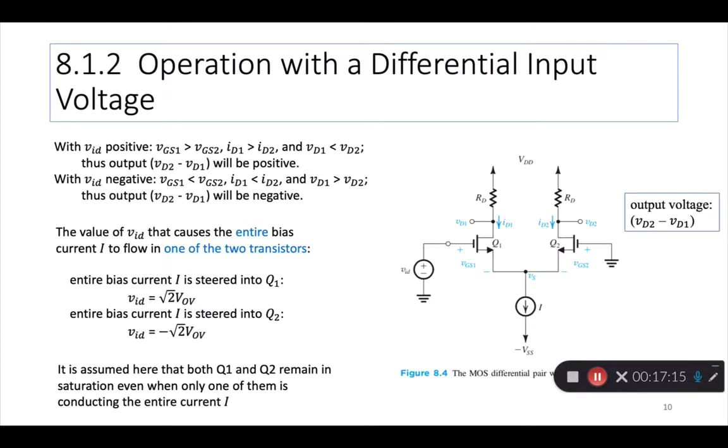Let's say we put 2 volts on Q1 and 1 volt on Q2, then the difference is 2 minus 1 or 1, right? That's the effective input signal going into the differential amplifier. So you can do it either way, but once you put in a differential input, that means the inputs are different between the two devices on their input terminals, then you get amplification.